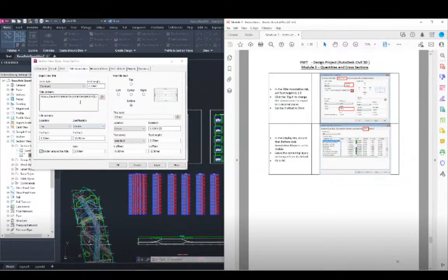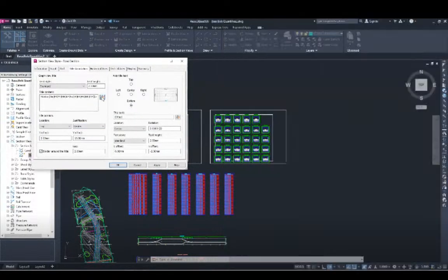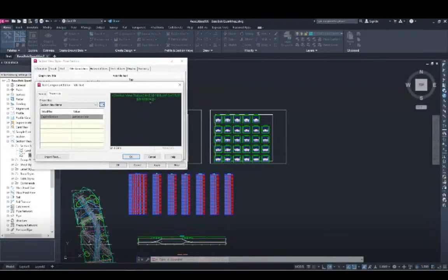So what you're going to do is click this A here. Now you're going to see in this display, it says P2. That means our precision is to 2 decimal places, but we want to change that so we have 3 decimal places of precision. So I'm just going to click this. We're going to go to precision here, go from 2 decimal places to 3 decimal places.